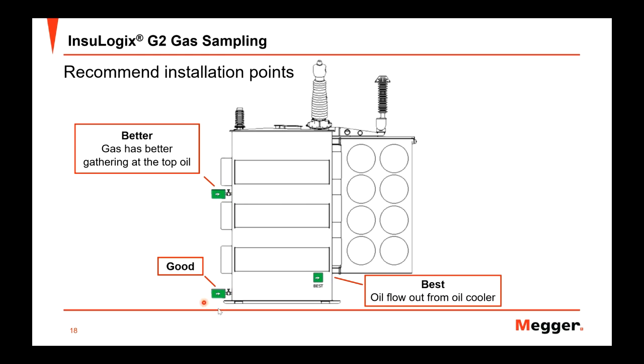This is a good position, but the best position should be here, the return from the cooler, because the oil will flow from the heat exchanger or the cooler, so you can sample the oil that circulates inside your transformer.